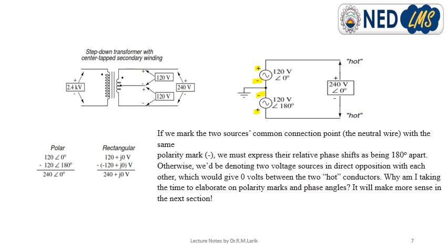They are used primarily to achieve a balance between system efficiency, low conductor currents, and safety, that is, low voltages. Split phase AC sources can be easily created by center-tapping the coil windings of transformers or alternators, as shown in this figure.